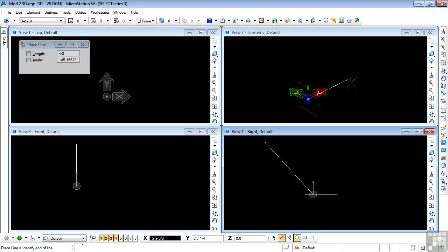Now, the next very important thing is that we need to orientate the compass, which at the moment, as you can see in the isometric view, is looking vertical. Now, the important point to note here is that the compass is vital to your drawing technique, since you're always drawing in the plane of the compass. And this is now a 3D plane, so you need to be able to move the plane around in order to draw within it. Now, in our case, we need to change this.